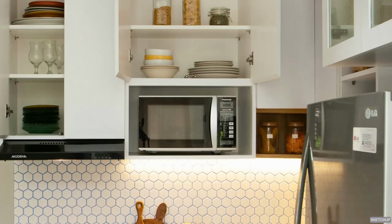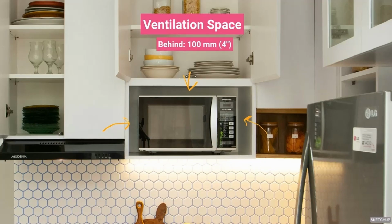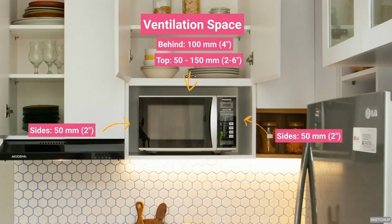Since microwaves can get hot, they need ventilation on the sides, the top, and behind them. Allow 100 mm or 4 inches of airspace at the back, 50 mm or 2 inches on the sides, and 150 mm or 6 inches on the top. I do strongly advise to check with the manufacturer, as from model to model this can differ.